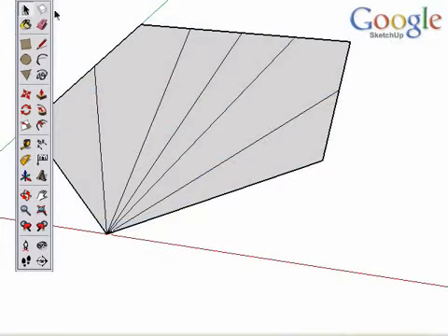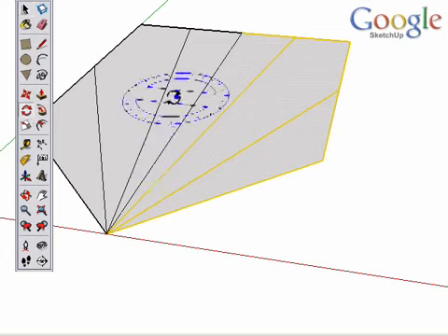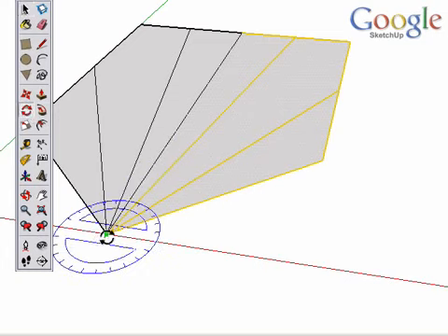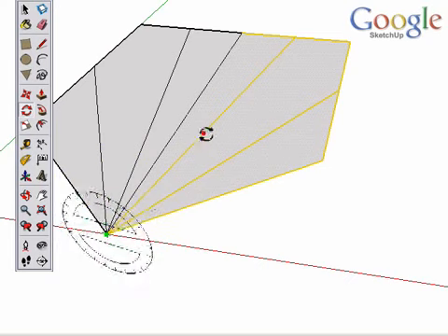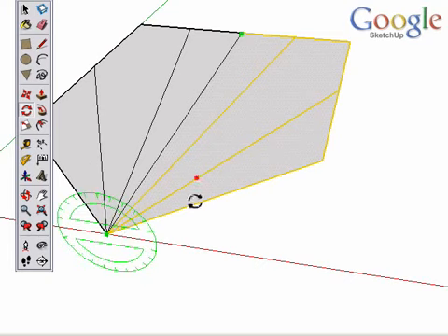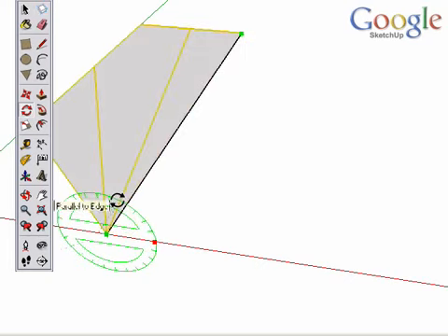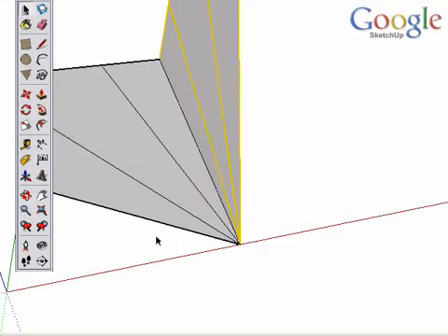You can also define the orientation by dragging your mouse button. Say we wanted to fold this surface up like a paper airplane. Click and drag the mouse from the center point, and you can see by dragging around, you can choose any orientation. Set the orientation you need, which for us is along this fold edge. Now proceed to rotate the surfaces up into the plane shape.